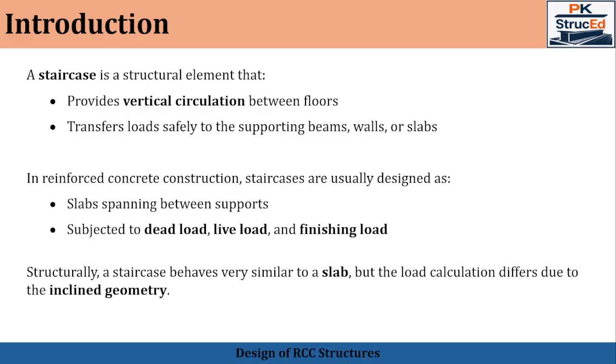Structurally, a staircase behaves very similar to a slab, but the load calculation differs due to inclined geometry. The staircases are designed as slabs, but loads are calculated carefully considering the slope and step geometry.